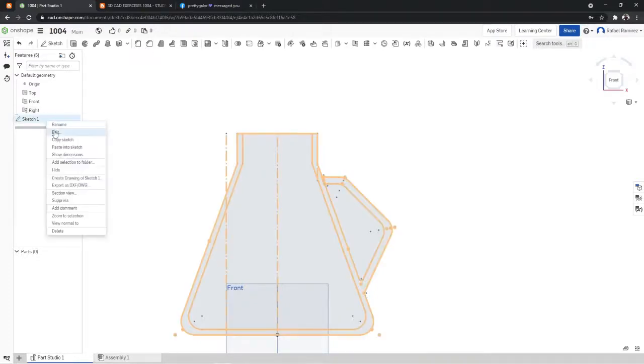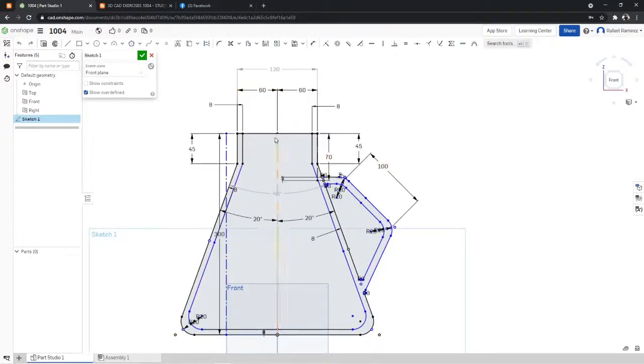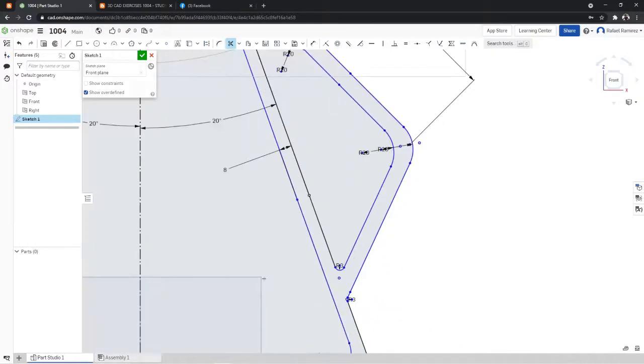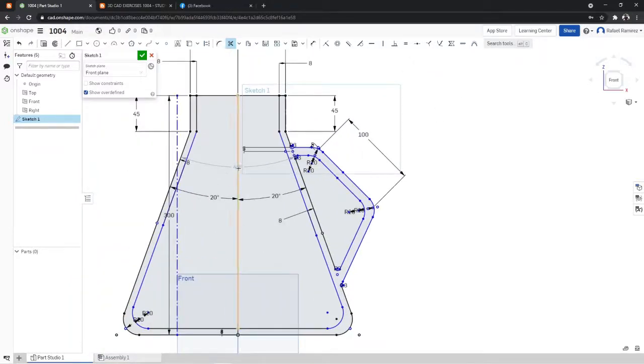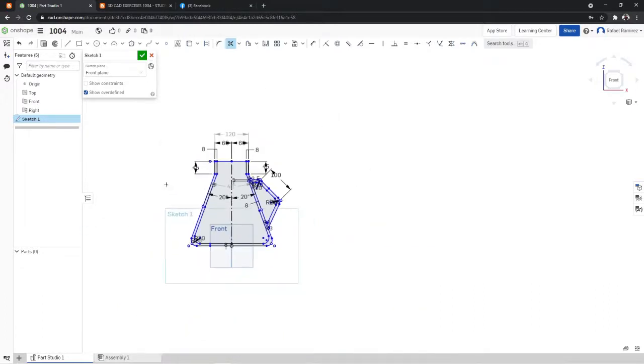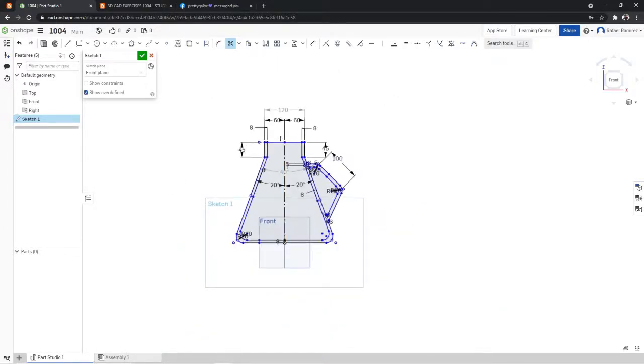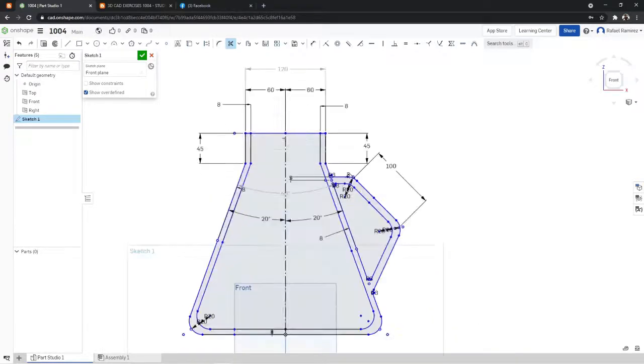So again, we need to click on edit sketch 1 to go back to our sketch. We need to remove excess lines. This one, we need to remove this one and this one. Removing excess lines. Do not remove that one. Sorry, just need to remove this line, because there's a reason why we should not remove the middle line: we can use this middle line as the basis of our revolve tool. I'll be able to show it to you later.